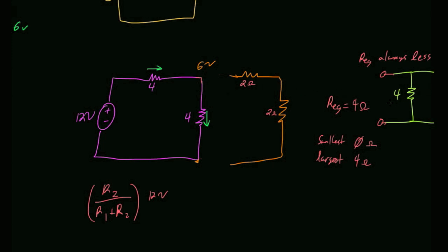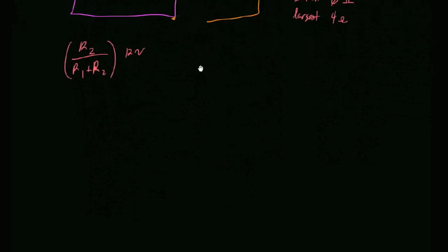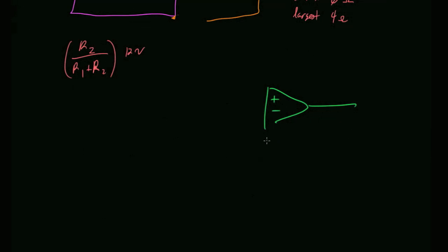Everybody remember op amps? Op amps got like 2 rules, right? What are the 2 rules? Inverted or non-inverted? Yes, thank you. That's the first one. No current goes into an op amp. You can connect whatever you want to this. The op amp will melt before current goes into it. Whatever you connect to it, it will not draw, no current flows in. It has an infinite input impedance.